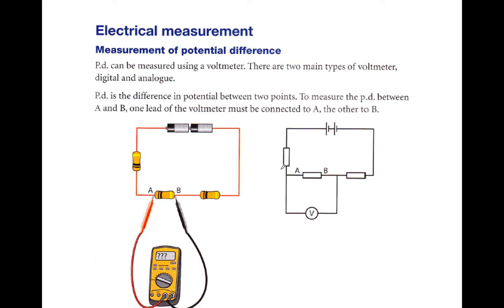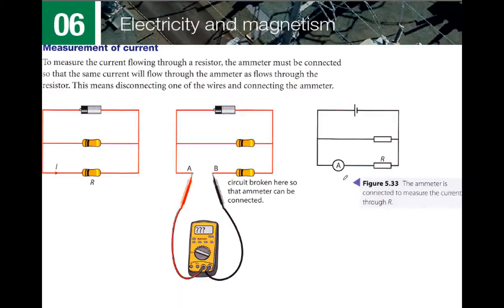And the answer is, if the voltmeter didn't have an unbelievably high R, then some of the current would flow in this and be like a parallel circuit. We don't want that. We just want to measure. We don't want to interfere with what's going on here.